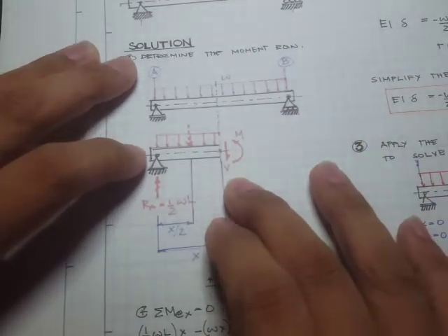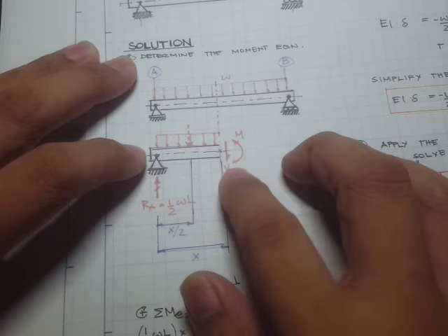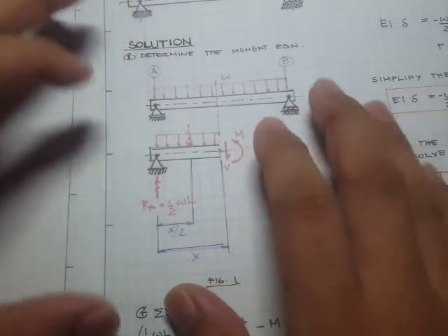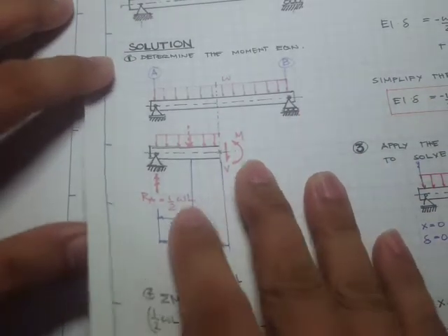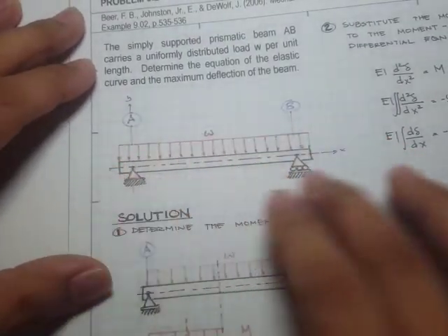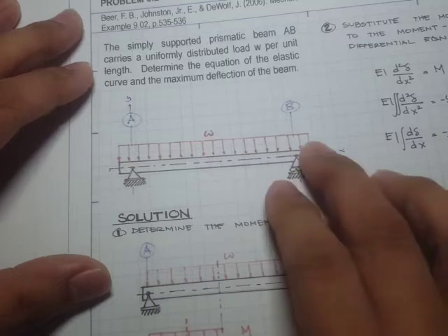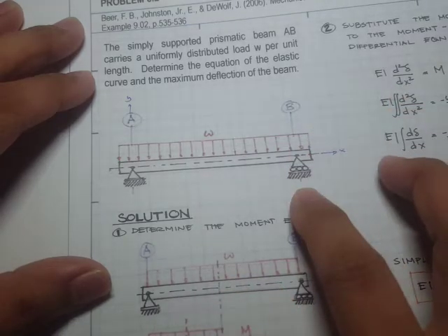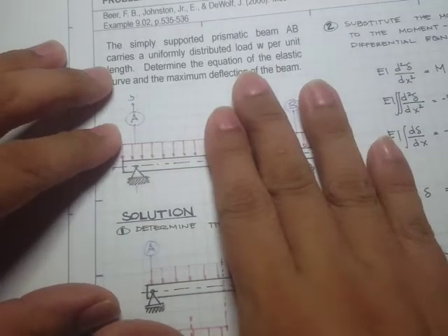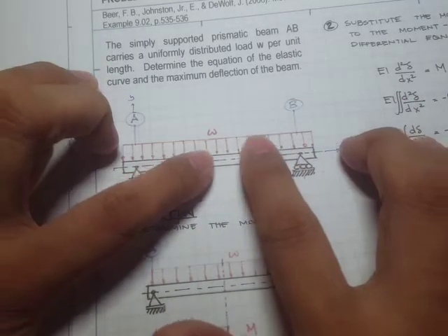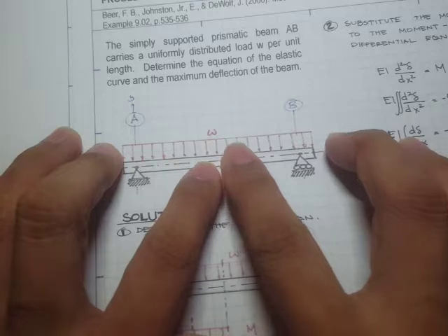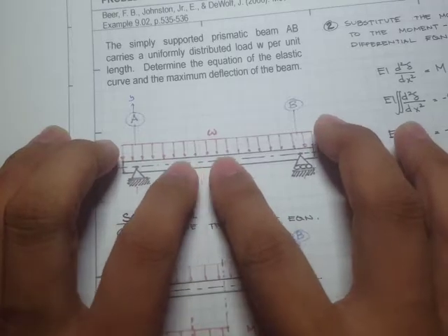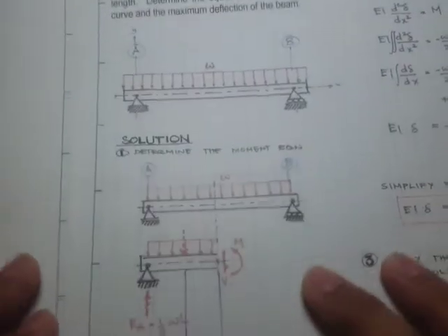So we made a cut, and then we expose the internal forces, the shear force and the moment, and of course we also have to determine the reactions at A. And the reactions, if we base it on this beam condition, it is symmetrical, and therefore half of this distributed loading will be carried by this roller support at B, and the other half will be carried by the support at A. Okay, so that's how it works if we have symmetrical loading, and also in terms of the lengths or distances.